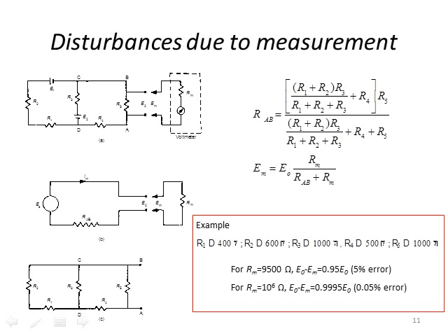The first thing that we should do is try to represent this circuit, which is not so complex, but it has two voltage sources and resistances, and we basically want to measure between points A and B. So we can make a Thevenin equivalent circuit between points A and B that allows us to easily make a transfer function of the system so we can assess the errors.